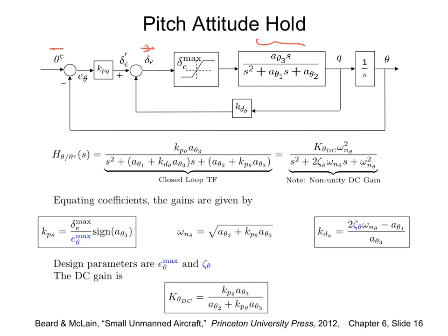So in the closed loop, Q can be considered as theta dot. So that's theta dot, you multiply by KD, and then your error goes in. You have the closed loop transfer function here. The only problem is if you find that DC gain, right? DC gain is S equals 0. When S equals 0, this is your DC gain, which is not equal to 1. Okay, so that's very important.